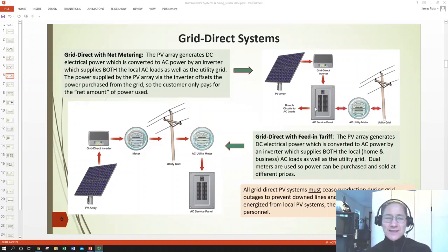So that's obviously a problem if you're looking to recoup the initial cost of a system in savings on your power bills. You don't want to over-generate if that is your sole goal. And so that unfortunately will lead to people undersizing their system because they don't want to be giving away the power they generate. So one solution to that problem of people basically having to give their power back for free is the idea of the feed-in tariff. And this is actually a form of subsidy of renewable generation.